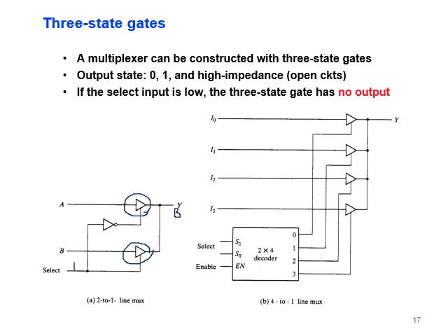If it is 0 here, then this will be 1, and this means that A will appear across the output. We can use this to construct a mux for 4 bits, as you can see here. For each bit, we need one of these devices.